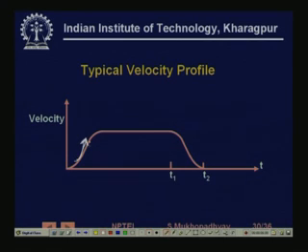After some time, as the velocity rises, the encoder pulses also go up, so on an average the counter gets incremented an equal number of times as it is decremented, and therefore the counter value is maintained.